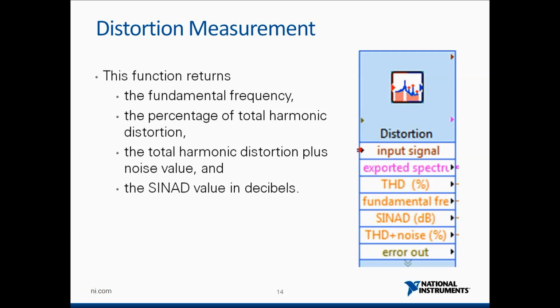If you give some input, let's say X, which is called a stimulus, you get some response, let's say Y. The system is supposed to have a transfer function, which is Y by X. That black box is doing something to X to transform it into Y. That we call the transfer function of the system. So this VI, if you give a stimulus and a response signal, can tell you what the transfer function of the system was.